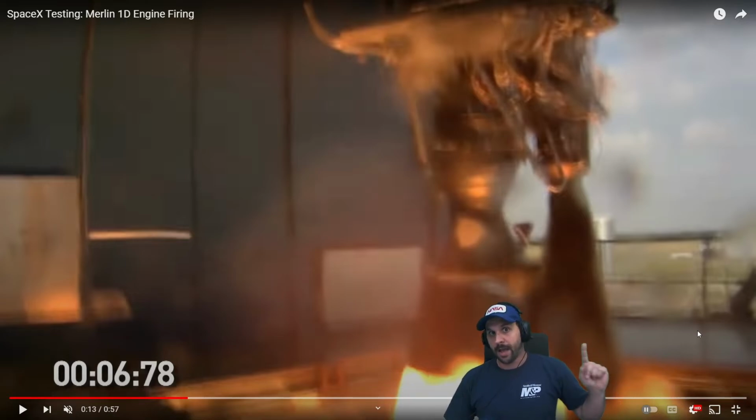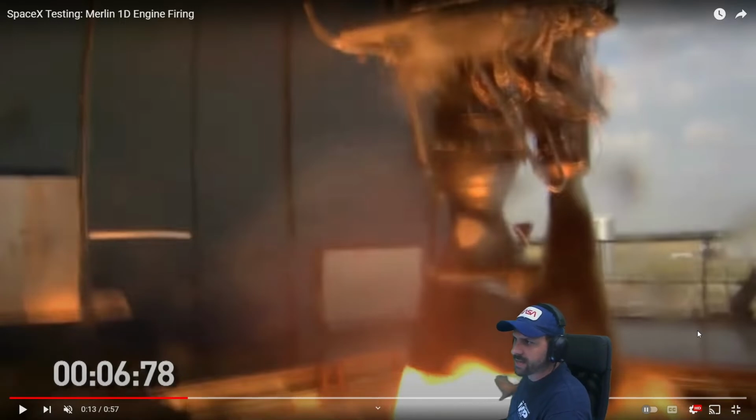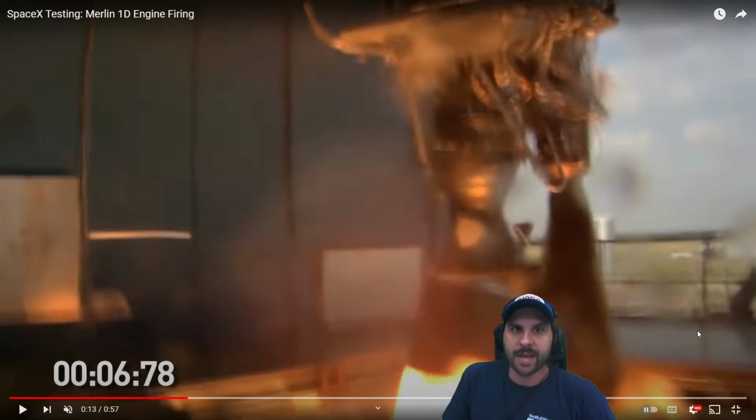That's the reason. Now, the other reason that they're running fuel rich is for temperature purposes. You guys ever wonder why some rocket engines could fire? Spoiler alert, right in this area right here, it's extremely hot. Right here. Not here or here so much. Not here, but right here. It's pretty damn warm. How does it do that without melting the metal? Well, rocket engines do not run anywhere near stoichiometric. They run extremely fuel rich to prevent the metal from melting.